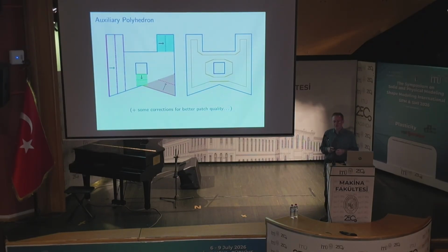The same can be done for all of the edges. An interesting example is the red one on the bottom, because now you can see that we are only interested in this wedge region shown in red, which is defined by the adjacent edges. So the maximal offset distance will be this dashed line there. When we have these maximal offsets computed, we use a fraction of these, some percentage, like 70%, to create the actual shrunken face.